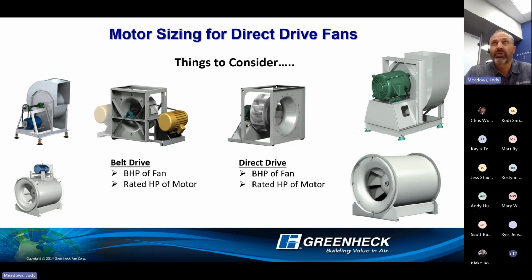Well, the same is true with a direct drive fan. So I'm again thinking about the brake horsepower of the fan at that design point and what horsepower motor I'm going to utilize. But the other thing that you also have to consider is fan RPM versus motor RPM. All right, and this is what I talked about a little bit earlier with sizing motors and wheels, sizing wheels to fit with nominal motor horsepower, nominal motor RPMs.